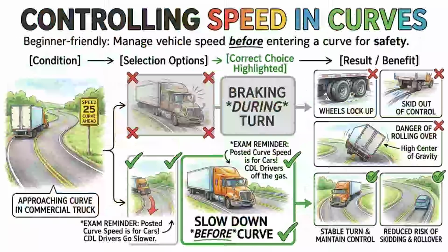If you are involved in or come across a traffic accident, you have a professional duty to secure the area and prevent further collisions. Your very first action should be to protect the scene by pulling your vehicle safely to the side of the road if possible. You must immediately turn on your four-way hazard flashes to warn approaching traffic. Then, you should set out your reflective emergency triangles at the proper distances to alert other drivers before they reach the accident. The exam will definitely test your knowledge of emergency triangle placement.